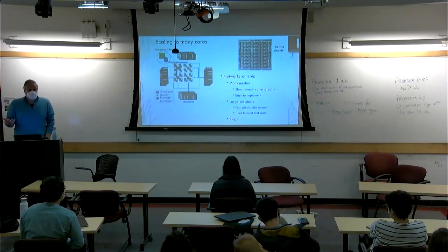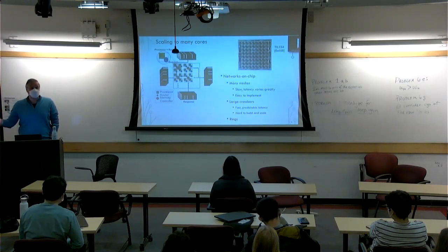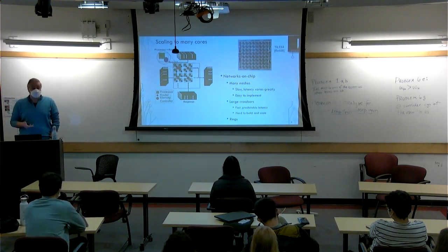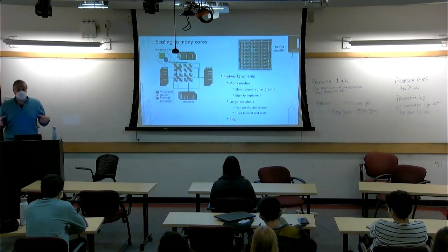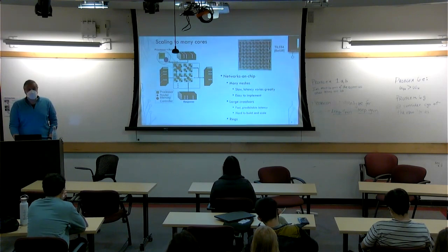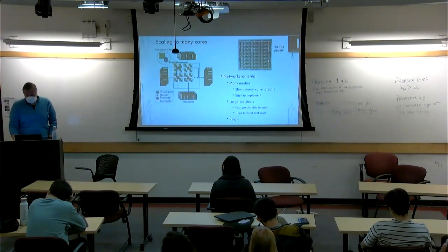And there are other types of topologies that we're going to go through. One example is a ring. A ring is actually very popular for a smaller number of cores, 8, 16, etc. You can find it in the Cell processor, and in a lot of the Intel architectures. It's simple and also scalable, but it has its own routing limitations and power and latency limitations. So there's a whole range of networks that people are playing with to try to balance this power, bandwidth, overall system throughput space.